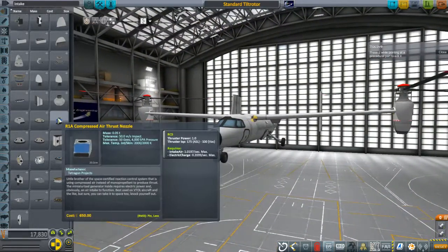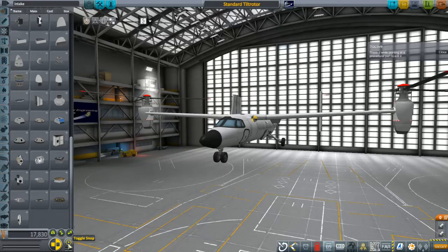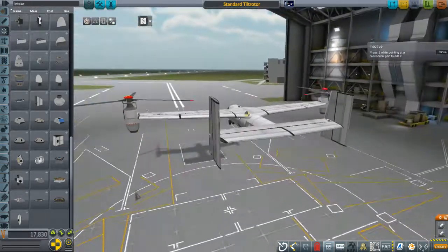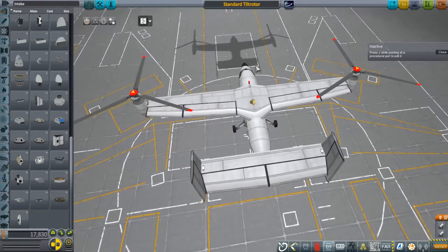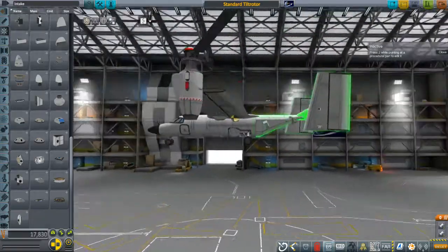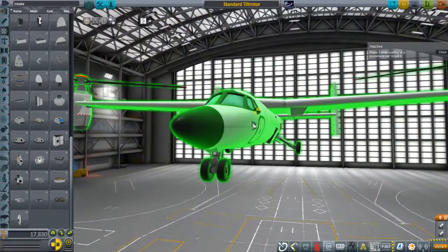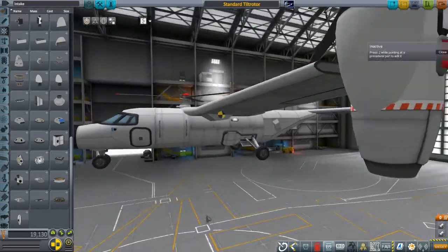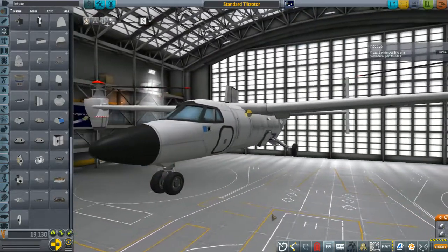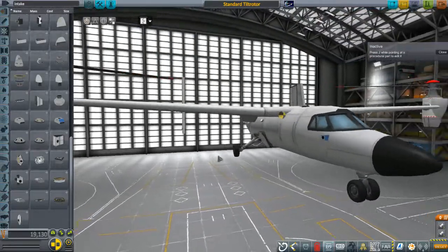Now, of course, because of the way the thrusting works, one of the other dynamics is if I put a left turn on my nose for yaw, it'll thrust out the left side here. But without a counter thrust on the other side, it's also going to try and push the whole thing physically to the right. So I want something a little over here, up front, that will act as a slight counter force to the thrust turns.